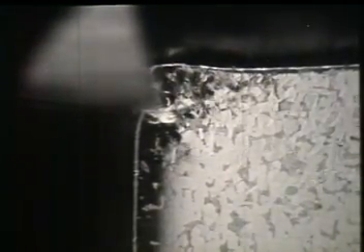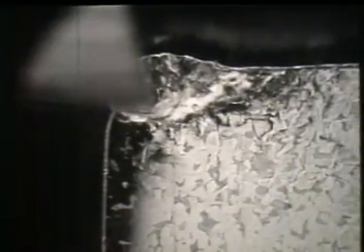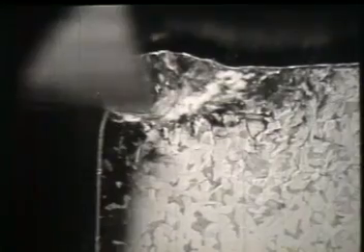Imagine a horizontal line extending to the right from the bottom of the tool point. Notice how the metal immediately above this line and close to the tool face moves to the right and upwards with respect to the material just beneath this imaginary line. This indicates shearing in the direction of cutting in the immediate vicinity of the tool point.